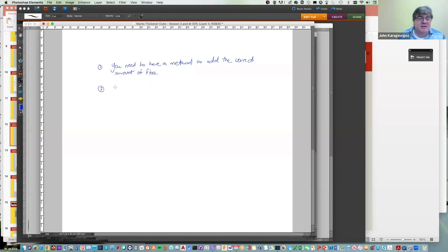The other one is you need to leave the particles in the thickener as long as possible, and I'll show you some slides on this. We'll talk about what that actually means and why. This is really important as well.